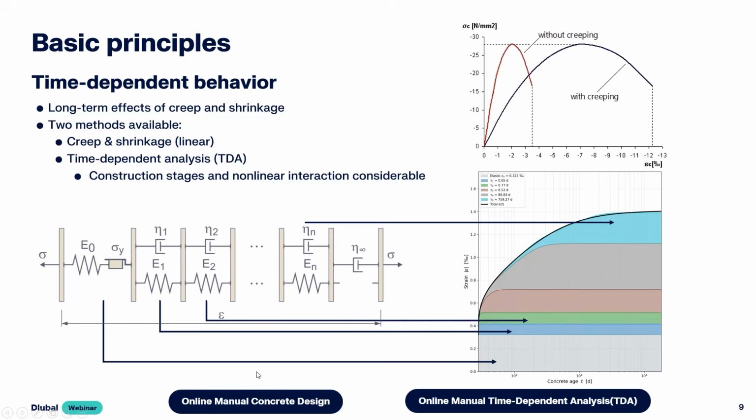This setup makes it possible to account for nonlinear interaction within our structures. These can arise from different creep influences, from load redistribution, or in combination with our construction analysis add-on CSA. Together, they allow a realistic representation of our construction stages, superimposing the different starting times and creep curves.